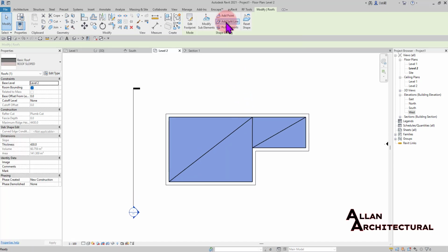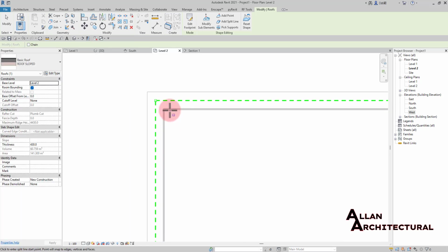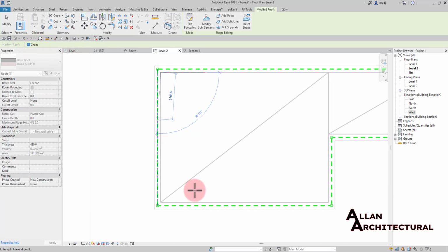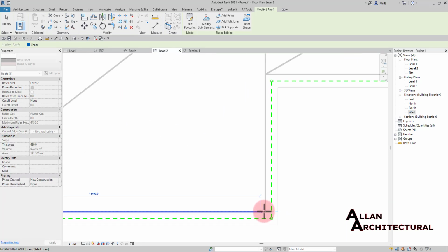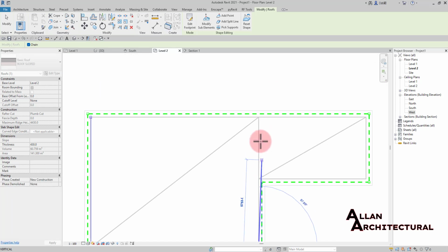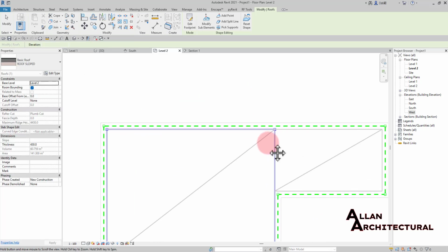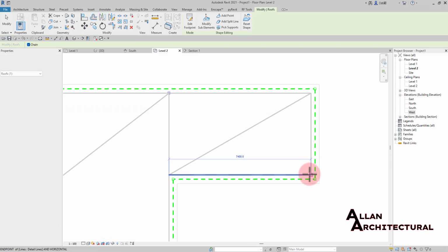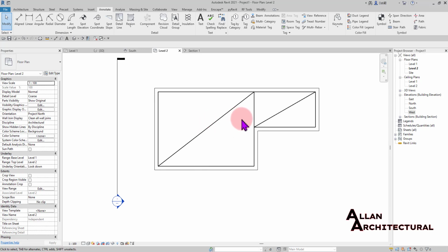So now I'm going to add the split line, and you notice it now snaps to the edges of our wall, which is correct. So we are going to draw this in there. I'm going to set this as a chain and just draw this in here, and also draw this all the way in here, and draw this in here as well. So escape, and also pick add a split line for this, and then we can draw this in here, then draw this all the way in here, and finish this. All right, so we finished that.